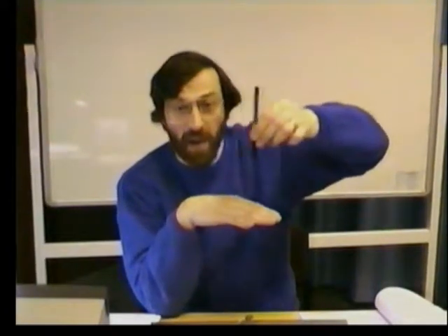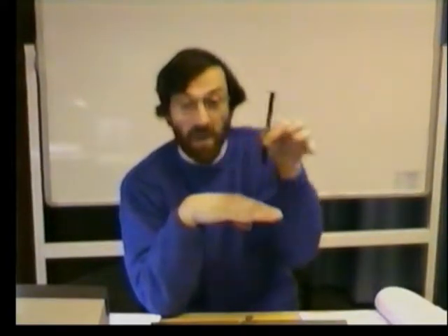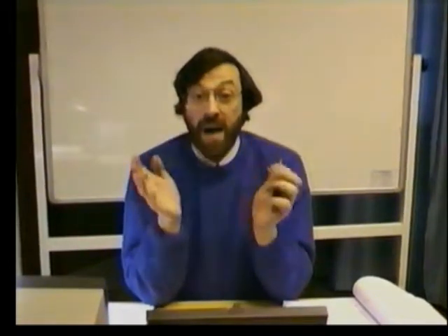It overshoots the position, the controller brings it back, and it starts moving backwards and forwards rapidly, trying to get in position. But because you're always a little bit slow in finding out what's going on, you've overshot, you end up pushing back, and in fact that's where the word comes from. It comes from the machine control problem, where the drill on the machine tool, or whatever it is, could be a lathe, the cutting tool rapidly oscillates around the hole it's supposed to drill, and the whole factory stops because they're waiting for a hole to be drilled. How do we stop this?